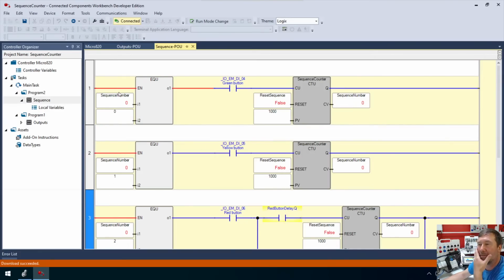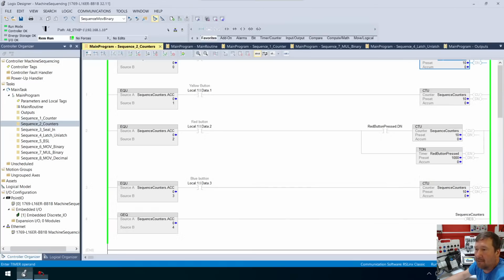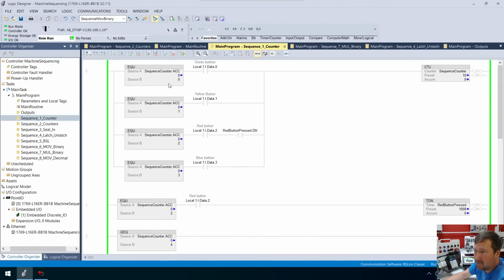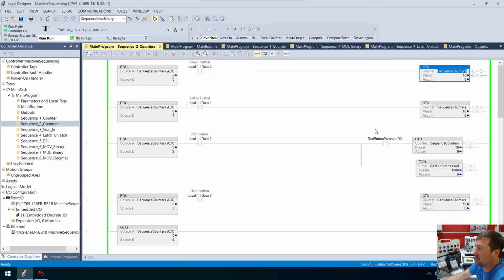Man, and here's where I was going to create a new program every time. And this is why, and I will do that from now on, I would love to go back and look. Well, I did create all the Studio 5000 programs. So we can see here, if we look at this one, this is the way it was written. But if we had 20 different conditions or 20 steps, it would be a real pain scrolling this and coming back up and figuring this counter out. Whereas breaking this up into the individual ones definitely makes it easier.